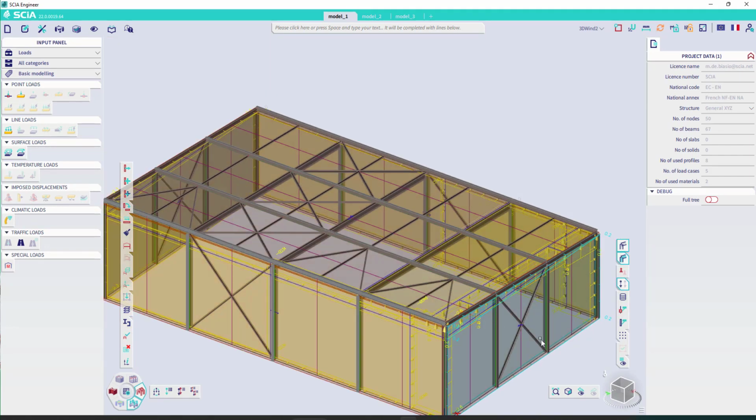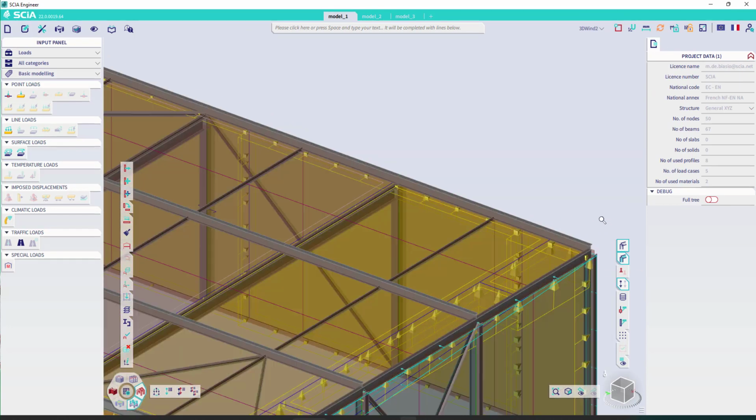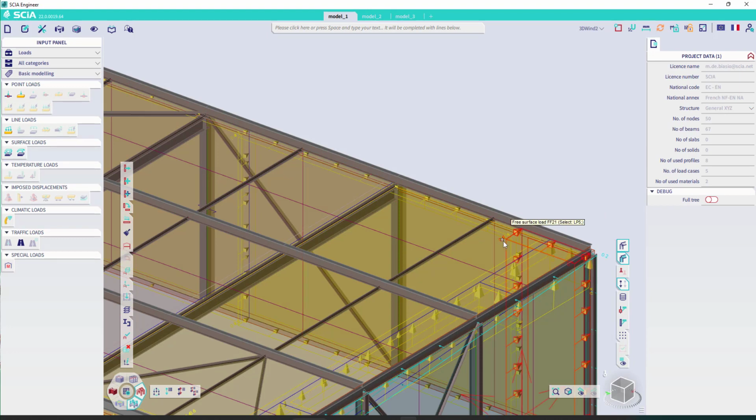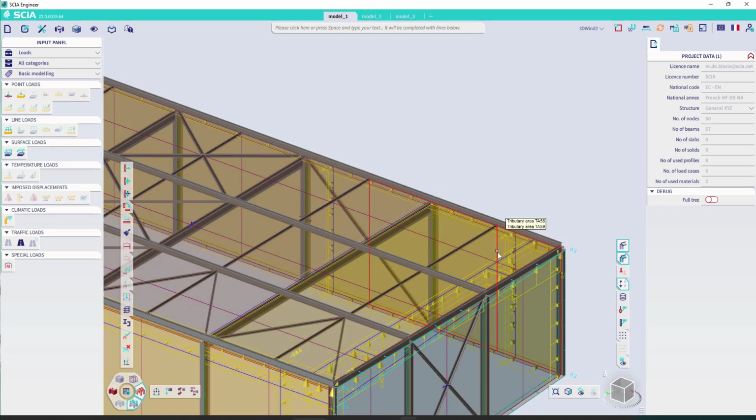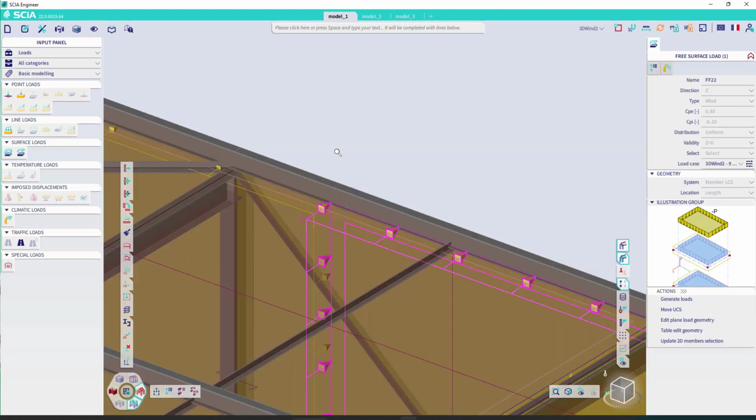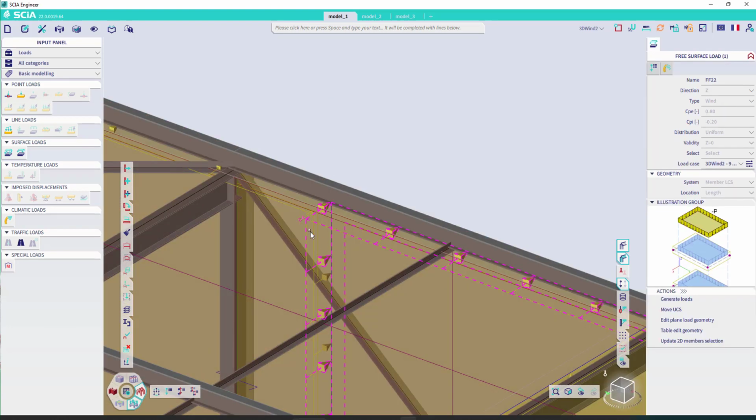This can also be something nice for you if you want to check the wind load that has been applied. Of course, as you can see here, with these colors that are quite light, it can be a bit difficult to see the numerical value. But if you change colors because you prefer this way to represent the net pressure, you can choose something a bit darker, and then you will have a clearer visualization of the net wind pressure.